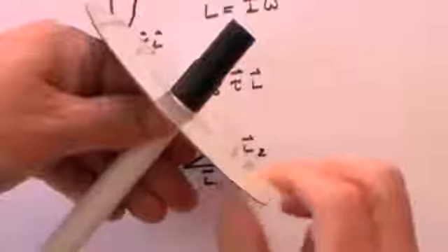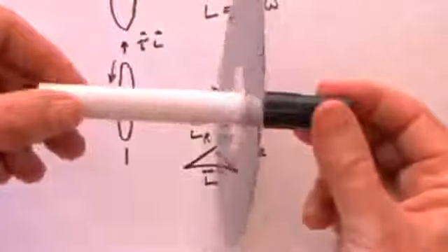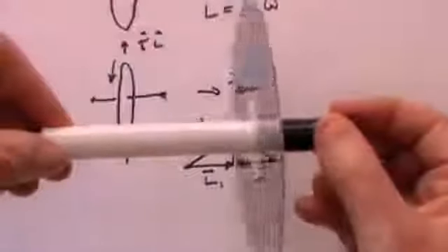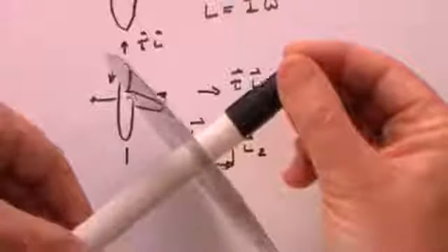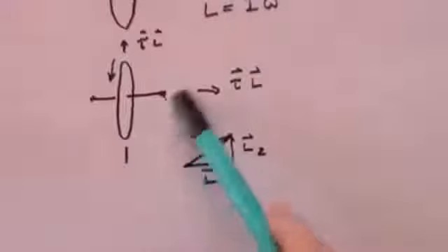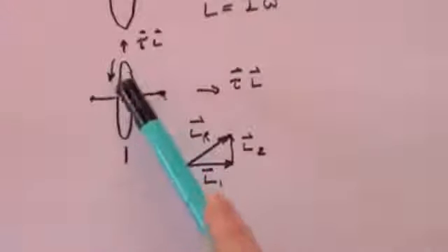It sounds absurd, and that's one of the peculiarities of a gyroscope. You think you're twisting it like that, but nature says, aha, you can't. And it twists your hand without you realising it, like that. And the reason that the disc flips to an angle of about 45 degrees, of course it would depend on what torque you apply around this axis here, but it will flip to about 45 degrees, and the reason it does so is to preserve angular momentum.